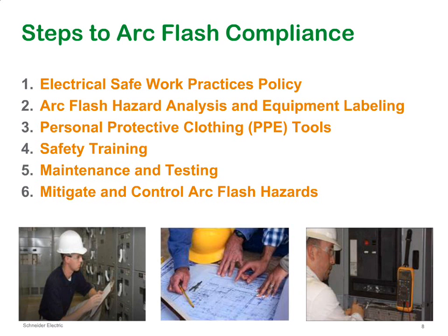equipment is, let's say, Category 4, that is not a suitable working environment for that worker, because getting into a Category 4 clothing suit is too cumbersome. It's too heavy, it reduces his dexterity and his motion quite a bit, and it reduces his eyesight due to the shielding. All of that could cause the worker to try to rush the task. Another issue with the heavy clothing is that it's hot in the summer. You can't really work in it for more than half an hour. You have to take it off after a while.